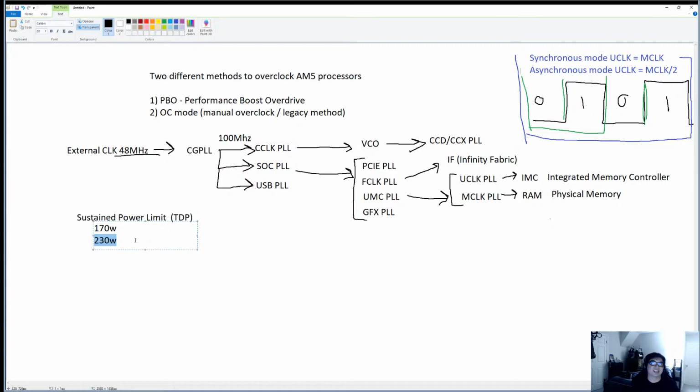But that's not a valid comparison, because in reality, the power levels on Intel are vastly different in terms of how the power draw relates to the TDP versus how AMD does theirs. AMD's is essentially the processor power that can be sustained indefinitely by both the power supply and the thermal solution. So your cooling system matters a lot with the new Zen 4 processors.